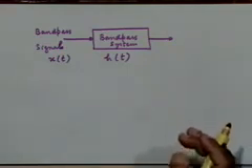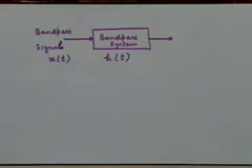That means it will pass a certain set of frequency components in the neighborhood of some center frequency f naught, right? And obviously it will make sense to have a signal which has frequency components in that neighborhood. If it does not have any frequency components in that neighborhood, the output of the filter would be identically equal to 0, right? So it makes sense that the input signal also has at least some components around that neighborhood, and let's say it is a bandpass signal in the same neighborhood, right? And you want to shape the spectrum of the input signal by passing it through this filter, right?